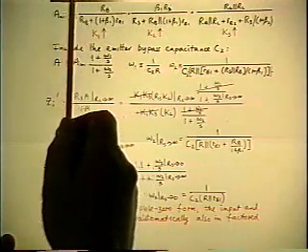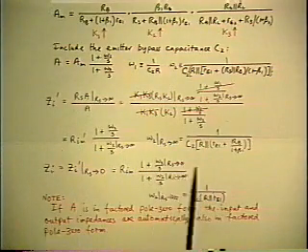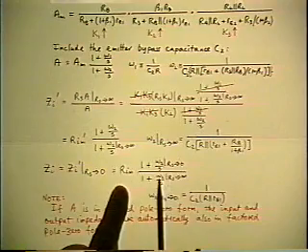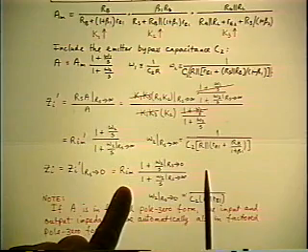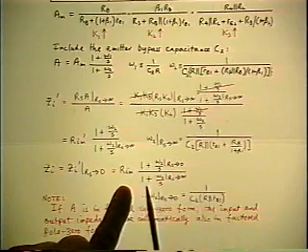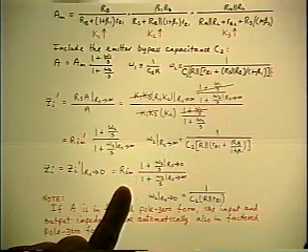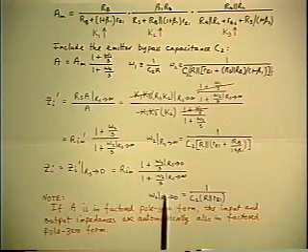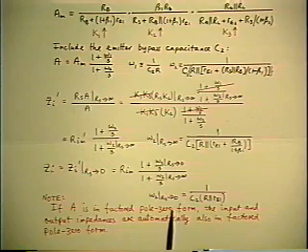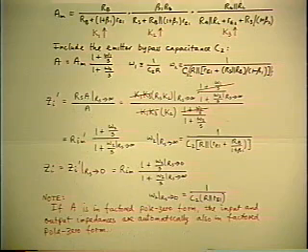And then suppose we'd wanted to find the outside input impedance, but we didn't know about the other version of the theorem. What you would have to do is take this, which has a pole and a zero, and add Rs. And to get the result in factored pole-zero form, you would have to cross multiply, add the powers of s, and refactor. Not that it would be that difficult in this case, but obviously a longer way, because you have to reconstitute separate pole-zero factors, whereas by using the modified version of the theorem, you get both results immediately in factored pole-zero form.